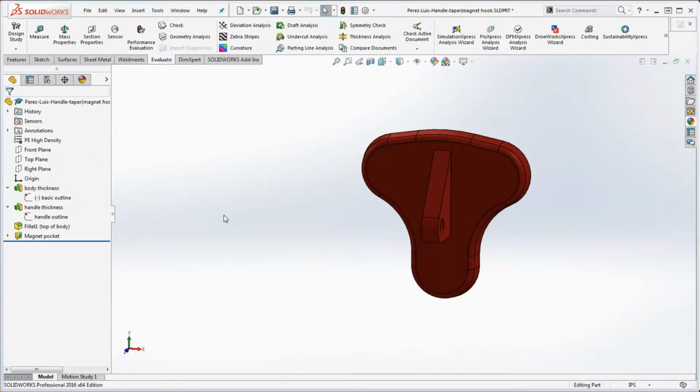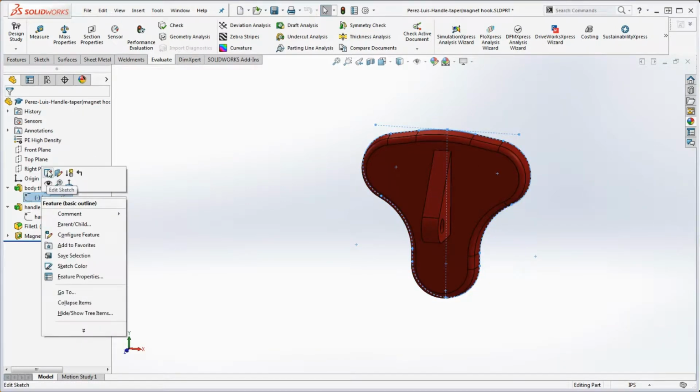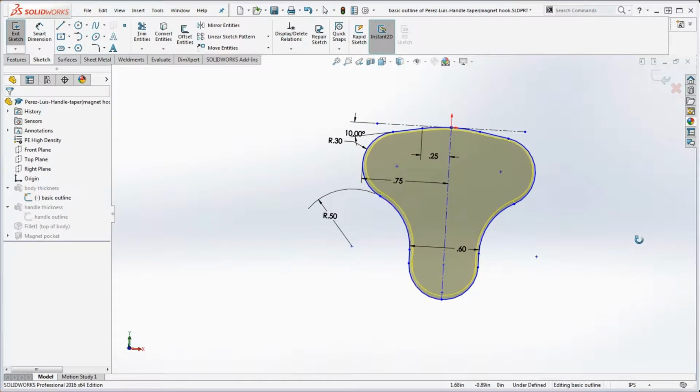And remember, you don't need to rename your sketches. Just rename your features. The only time you might want to rename your sketches is if it's part of a feature like a sweep or a loft, where you need to find out what the path or the profile of that sketch might be. It just makes it easier to select. So for the first part of the class, we're just naming our features. Don't rename the sketches. So we're going to go to our sketch one down here and take a look at this and see what we need to do.